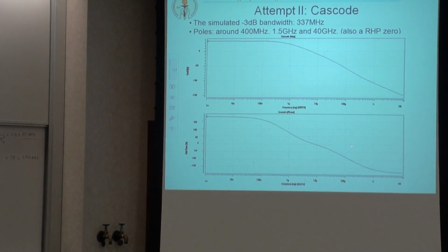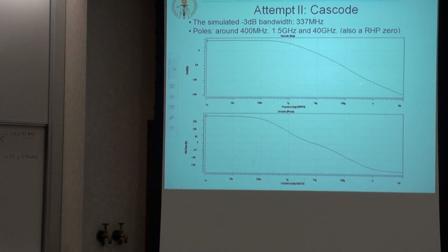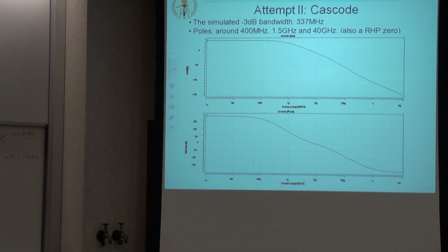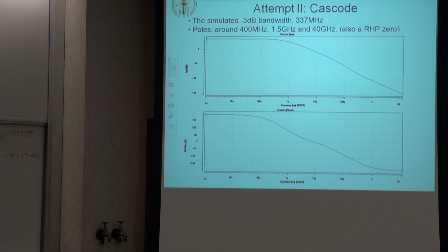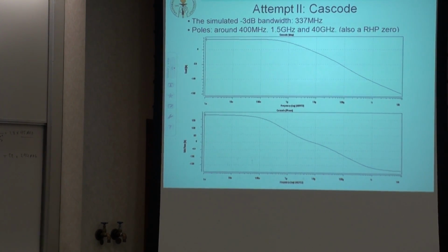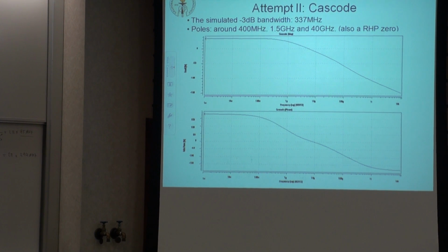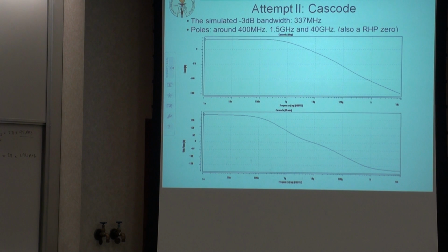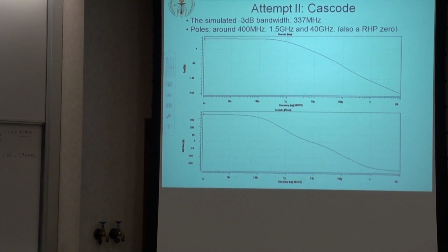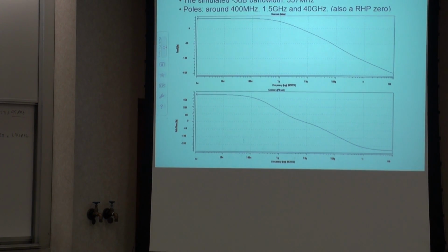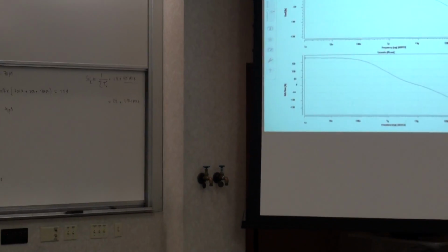And you can see that the 0 is at very high frequency, basically happening around here. It's close to several hundred gigahertz, which basically makes sense. It's above the cutoff frequency, it's above the FT. You can calculate the 0 too. We have done this before. It's GM over C mu, the frequency, right? Anyway, so we improved it by a factor of 3-ish.